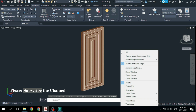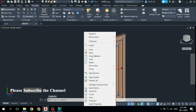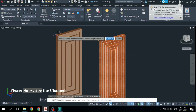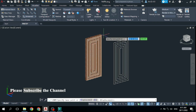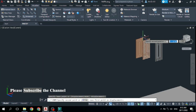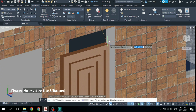these 2 doors. And after that, select this door and right click and move it, specify this is your base point and move it, and leave these rectangles here and then select it and copy it, copy selection and specify this midpoint as your base point and come to this opening and sit at these openings.